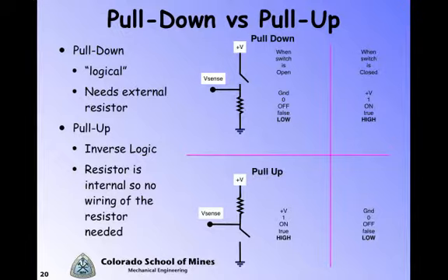So all of those things mean the same thing. In contrast, when that switch closes, you can see that the potential for V-sense will then be drawn down to ground potential, and in that circumstance, it's at ground, it's 0, it's off, it's false, or low.